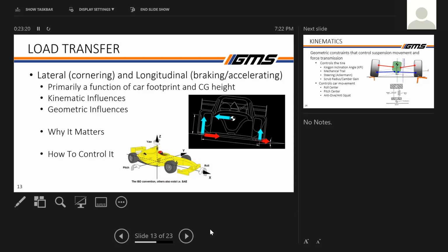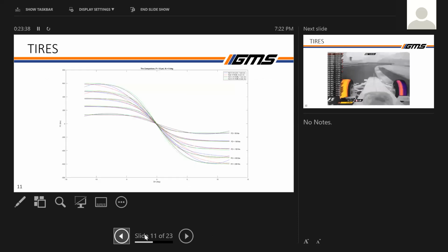It's all statics, forces and moments, and you can pretty much quantify right there that our yaw acceleration is going to be better. And then also more of the base, like compound and whatnot, that also goes back to the tire data that we get. You can see we tested the bigger tires on this as well, and we can go through this whole process for compound and size a little bit as well.